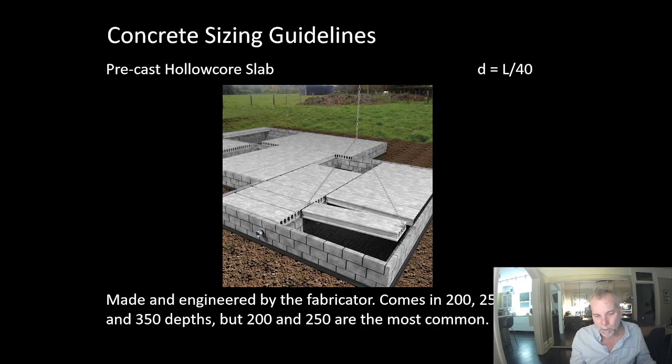Major disadvantages with hollow core. One is floor flatness. It's pre-stressed, so the tendons are put in tension. The concrete is placed and cured before the tendons are released. That means the concrete in the panel is in compression. That's wonderful from a spanning point of view because we take the tension out. The concrete doesn't crack, and if it doesn't crack, it's stiffer. There are tremendous benefits to that. But it means they tend to bow due to the pre-stress, so floor flatness can be a problem.